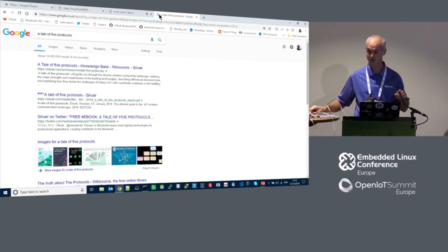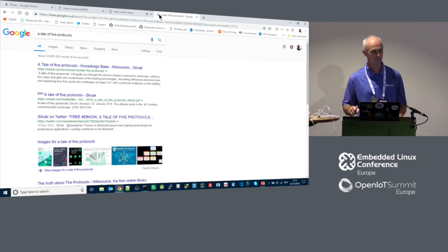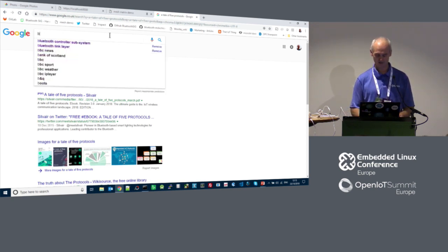By the way, it's 67, so 64, 65, 66, and the web application itself is part of my network because it's been provisioned. Okay, so short answer with little value is 32,767. That's the maximum number of nodes you can have in a single Bluetooth mesh network. But then our brains kick into gear and we start to ask questions about density, verbosity, how much messaging is going on. Is it sensors that are communicating a lot all the time? Is it light switches that get pressed once a day? Entirely different scenarios.